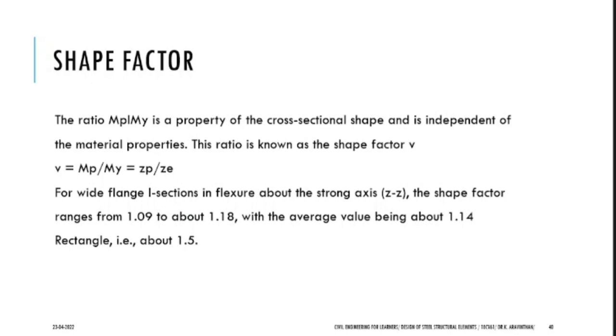And shape factor is the ratio between Mp and My. What is Mp? Plastic moment. P for plastic, M for moment. Plastic moment divided by yield moment. So what is shape factor? You just have to divide the answer. What is the answer? Mp by My.